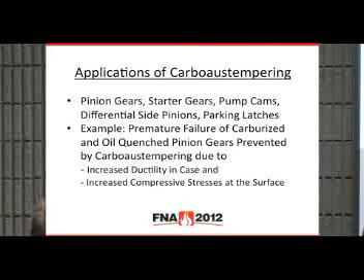Applications of Carboaustempering: various types of gears and automotive components. And as an example, premature failure of a carburized and oil quenched pinion gear was prevented by switching to Carboaustempering, because it provided greater ductility in the case, and it also increased the compressive stresses at the surface.